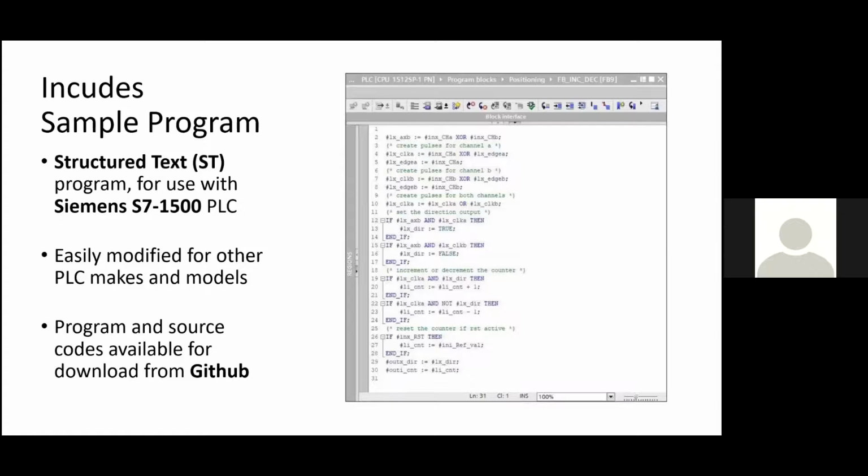Now, as with the first of the 24-volt models we've looked at today, each of the workstations of the 24-volt variation of the Training Factory Industry 4.0 model have a relay board for motor polarity reversal and both the multi-pin connector, again 34 pins with a grid of 2.54 millimeters, along with PCB terminals with pushing connections for all inputs and outputs. Now, all of this information and more is available in the 152-page PDF manual, which you should be able to download from the Fischertechnik website or from the Studica website.